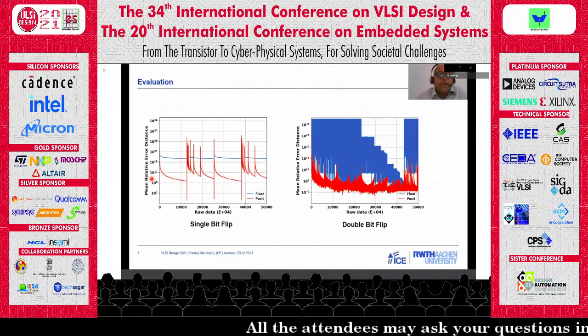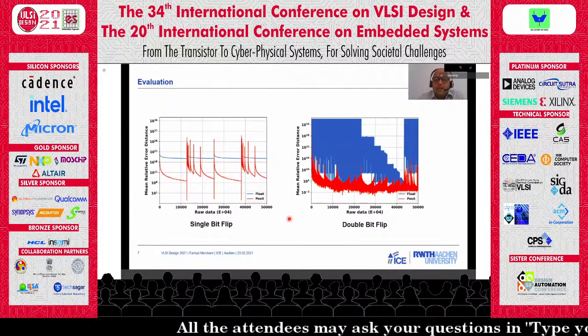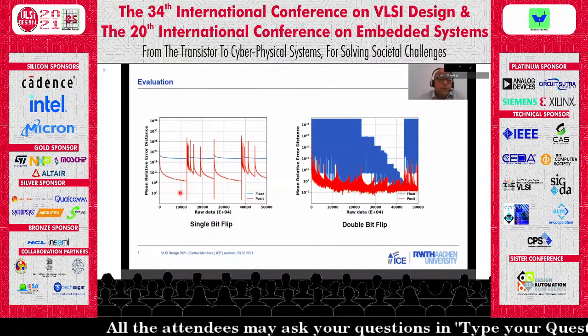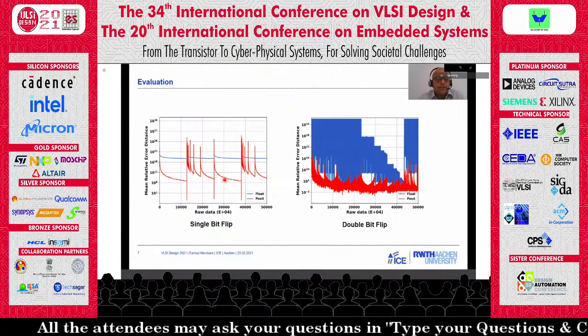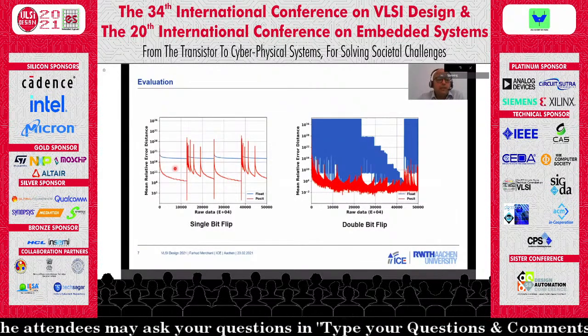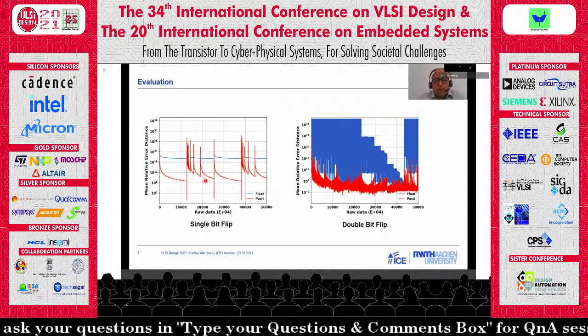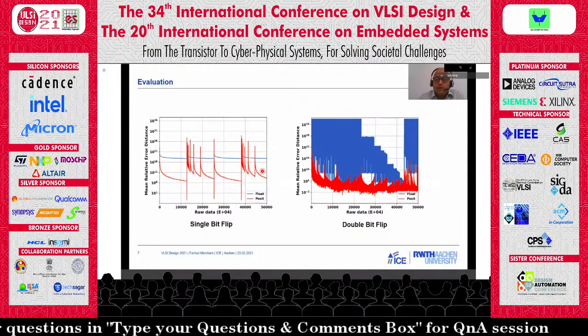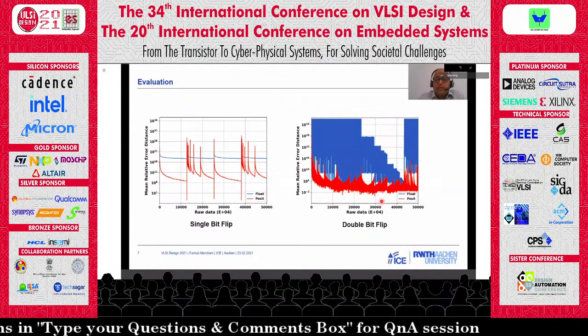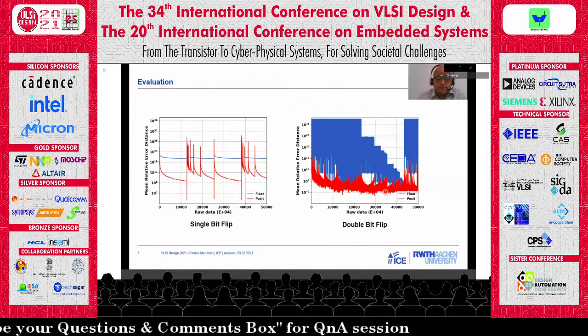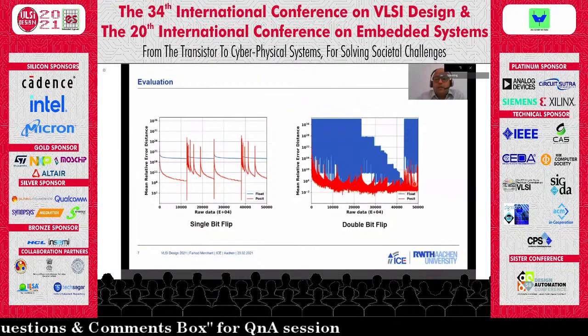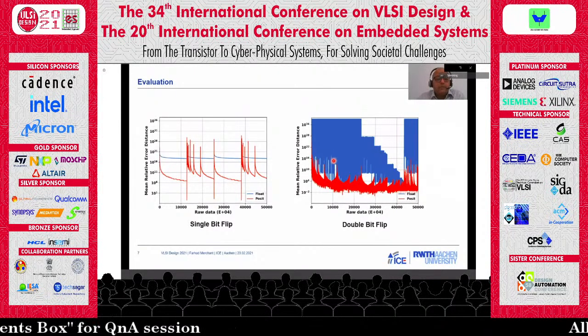What we observe is that for single bit flips the error is usually lower in POSIT compared to its floating point counterpart, and also when we introduce double bit flips, the error that we incur is lower than in IEEE 754 counterparts.